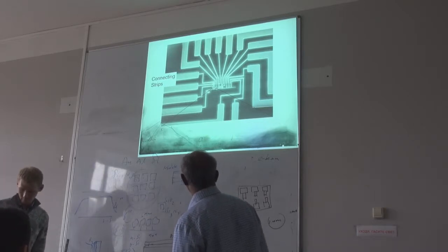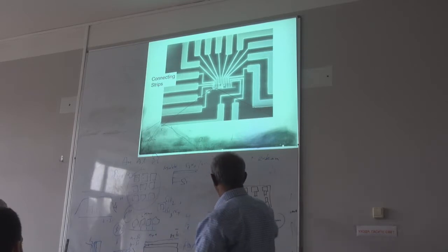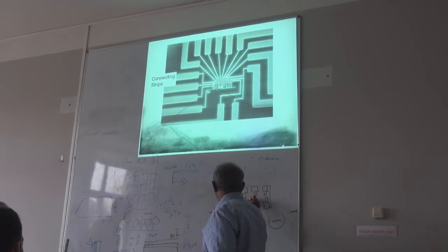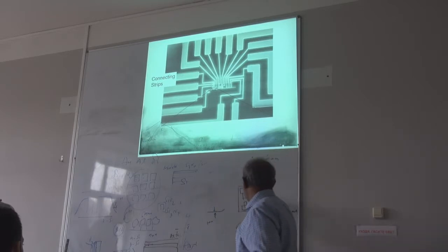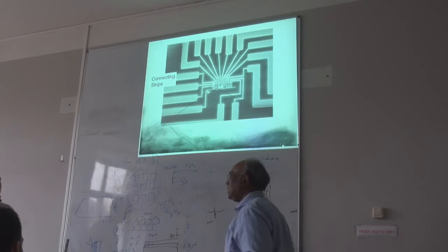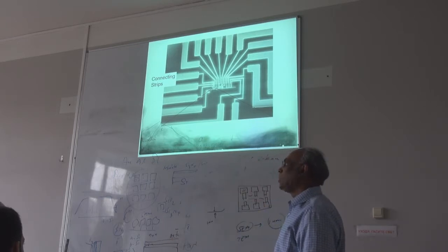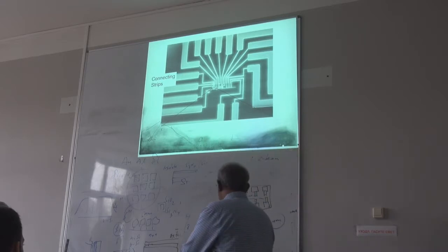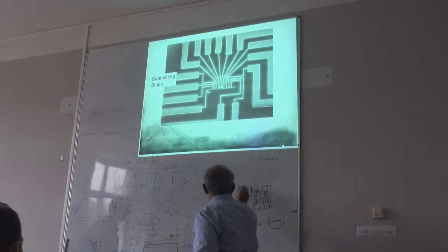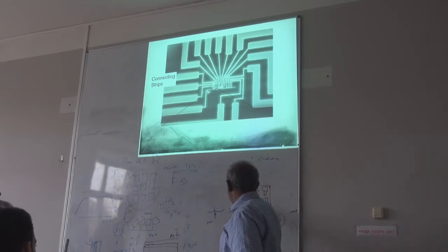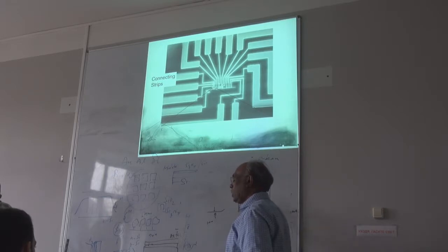Then we take that substrate and grow carbon nanotubes. So then what you have is something like this, or maybe something here, or maybe something here. Now I want to make connection to two of these leads, right? For that you have to do the e-beam lithography. Since we still have these alignment marks here, we have some idea about this nanotube location.